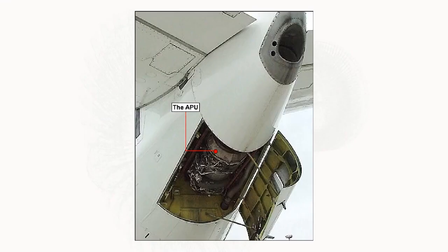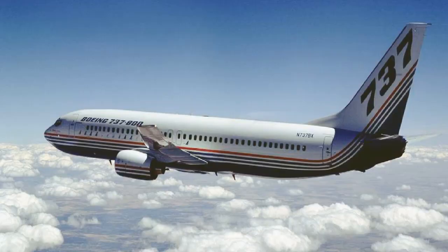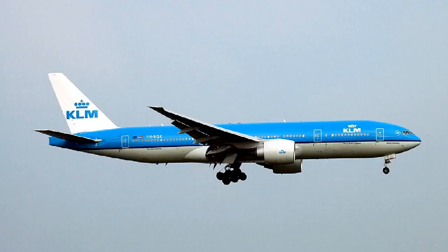The auxiliary power unit is normally positioned in the tail of the aircraft, where its operation will not harm personnel working in proximity to the aircraft. The auxiliary power unit of modern aircraft can be operated in the air, thus providing a backup source of power to the aircraft systems in the event of an engine failure. This ability to operate while airborne has become more important with the introduction of twin-engine aircraft, which are now flying long-haul routes under Extended Twin Operations (ETOPS) regulations.